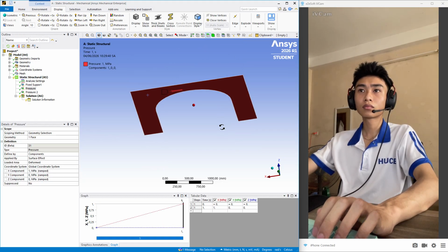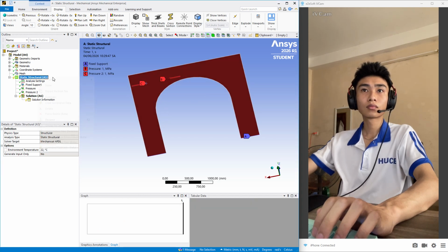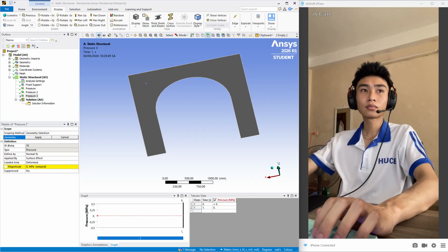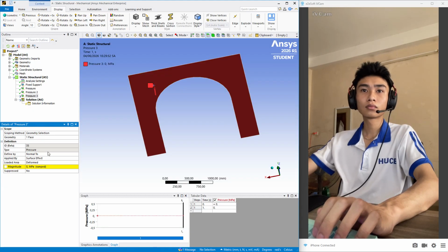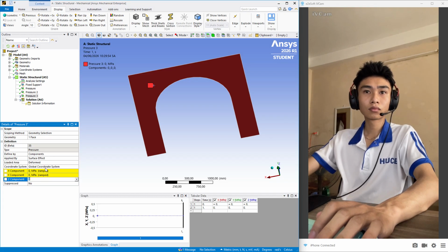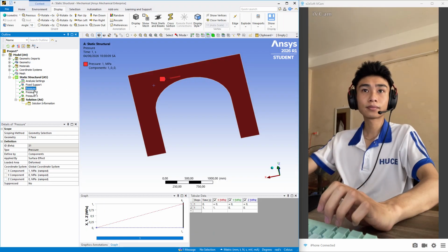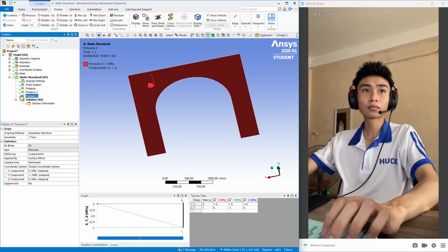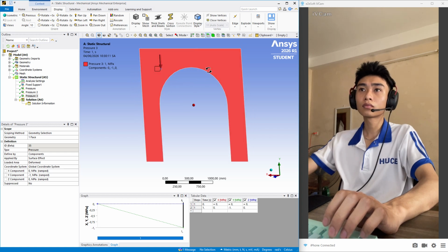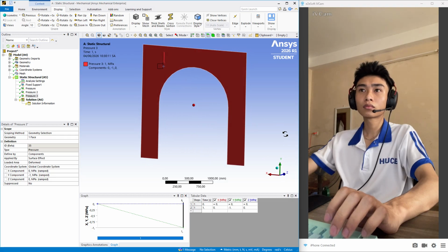Now again I will go to the pressure, select same surface, apply, and instead of normal to component, and here I am applying minus y direction, minus 1 megapascal. So minus 1 megapascal is applied, so you can see the conditions: x direction 1, then opposite direction again 1 megapascal, and downward 1 megapascal. So all the loading or all the pressure conditions are perfectly given.